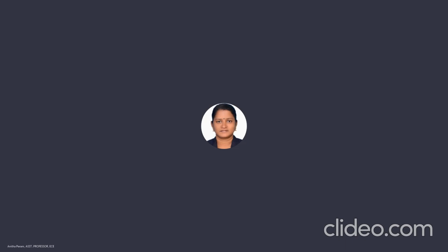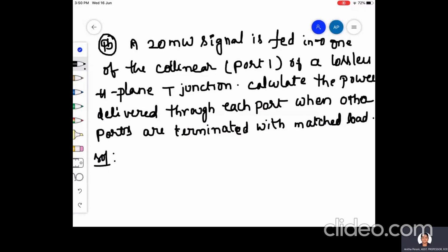Given a problem on the H plane T, you can observe that they are specifying a 20 milliwatts signal fed into one of the collinear ports. We know that the H plane T has 3 ports. It's a 3-port device. Port 1 and port 2 are called collinear ports, and the other port we call the H junction or H port.